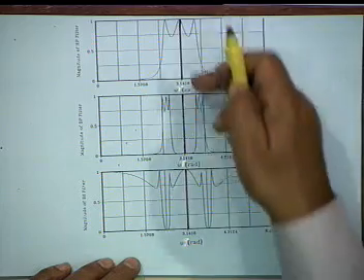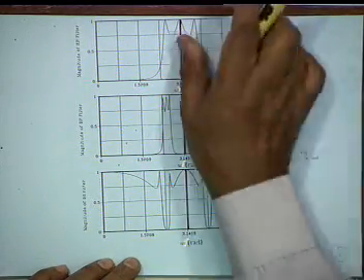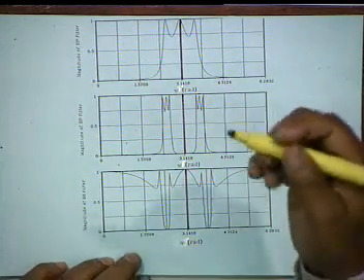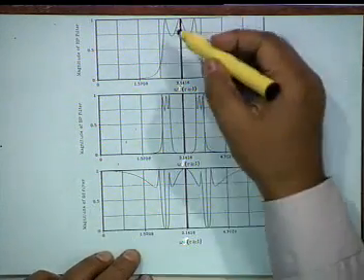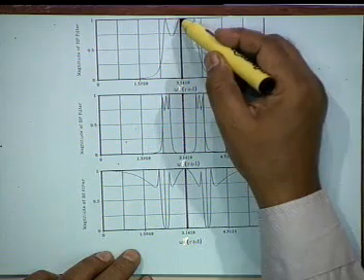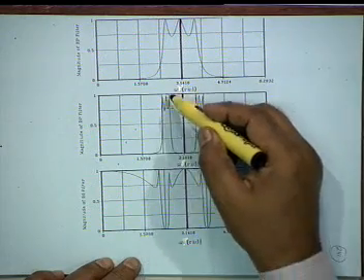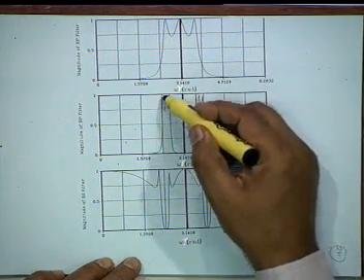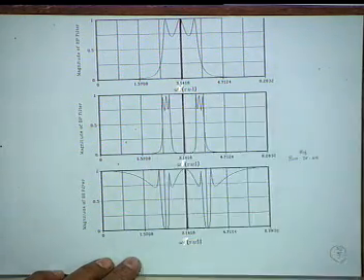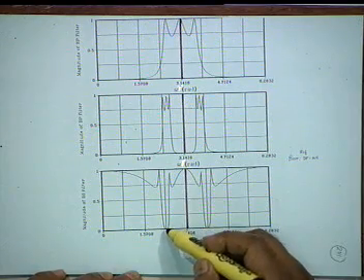For example, I have put this red mark to show that our base band, our interest, is only up to this. You see, it is a digital Chebyshev, whose prototype was a Chebyshev filter, so there are ripples. And it is a third order, so 1, 2, 3 peaks and dips. High pass, then this is band pass, and these are the band edges. Center frequency is somewhere here, we do not care where it is. Similarly, this is a band stop filter.